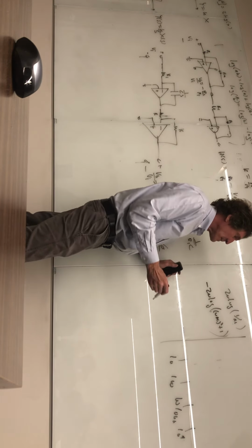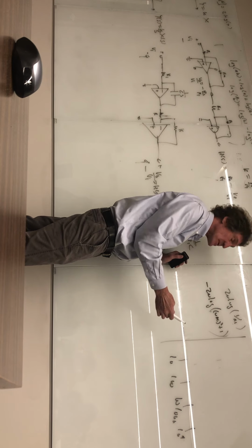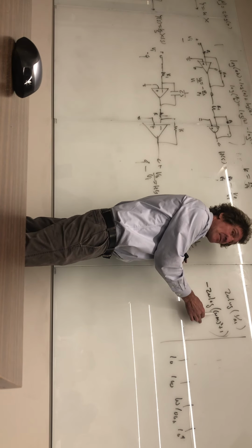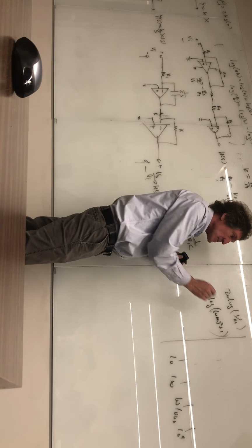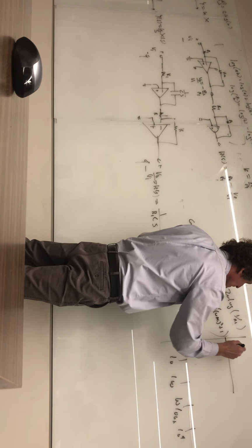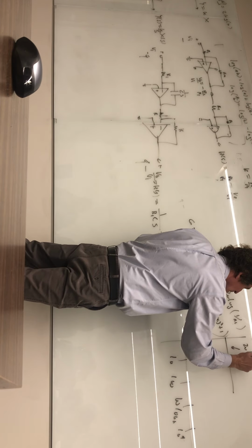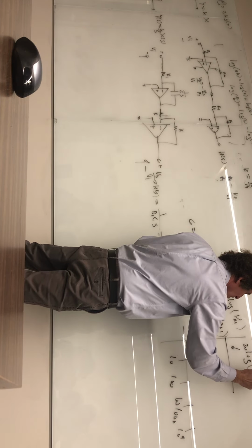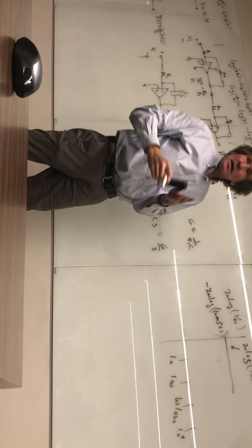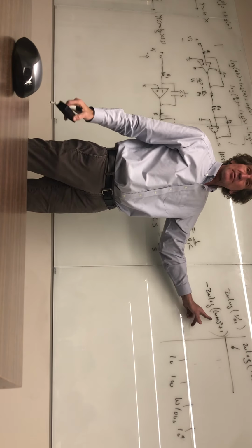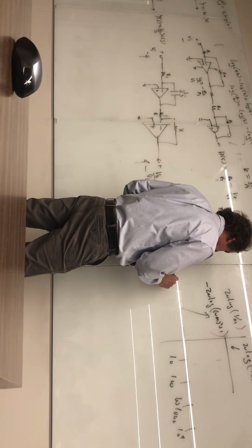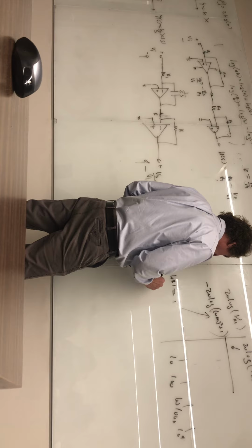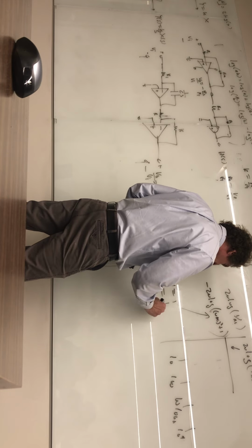If you look at this, what happens when omega is very low frequency, very low? Well, something very small, right? Plus 1 is about 1. The log of 1 is 0, correct? So you start out with just this term. This is simply 20 times the log of 1 over RC. It stays that way until this becomes appreciable. And the point where it becomes appreciable is when omega RC equals 1, or omega equals 1 over RC.